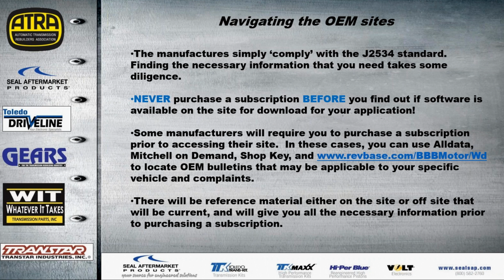Now, in the case that we're not able to get into the OEM website, we do have aftermarket resources like AllData, Mitchell On Demand, ShopKey, and there's a website that you can go to called www.revbase.com, as listed on the slide. And we can actually view information and documents and bulletins that would be relevant for programming needs that we might have for our application or complaint.